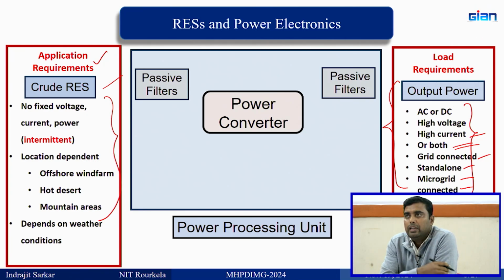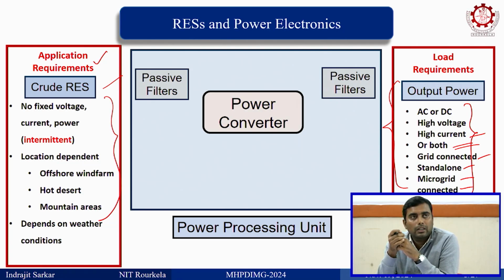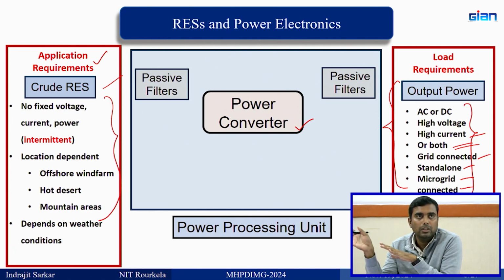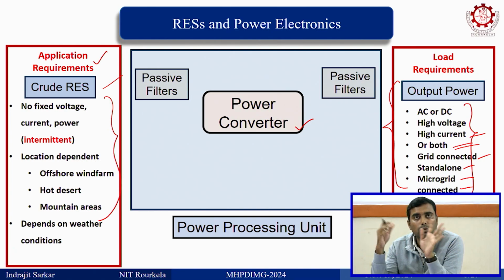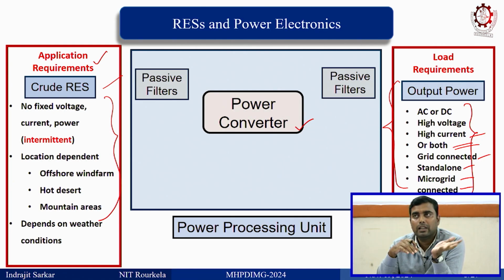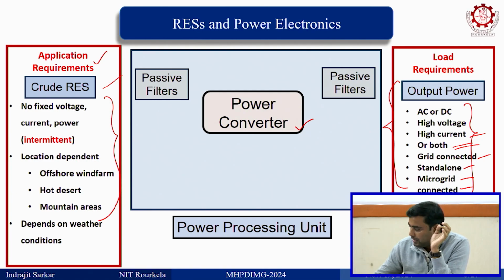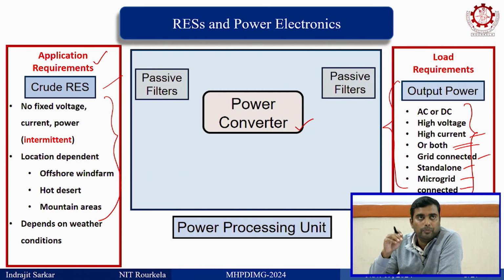So when I studied power electronics in my BTech, my professor first told us that power electronics is not about dealing with high power. Power electronics is the area where we convert, with this power converter, one type of electrical energy to another type. So if DC is there, you are converting DC into DC, but the types are different, voltage levels could be different. Similarly it could convert DC into AC, AC into DC, AC into AC, everything is possible. So power electronics does this. So the power converter is there. The power converter is the circuit.